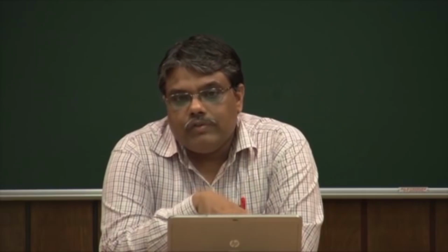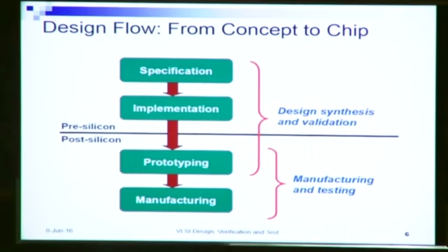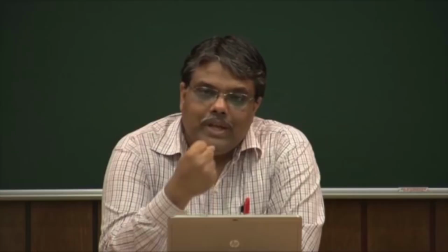So firstly, we don't have any idea about what the structure of the chip will be, what will be the gates, what will be the architecture. We don't have that idea initially. Initially, we have only an idea of the behavior or the functionality. What function should this chip or my application perform? And we jot it down in the form of a high-level C-like program as processes which communicate among themselves. So each process could be a module, and the modules communicate among themselves, right? So we have basically a program of what we have in mind.